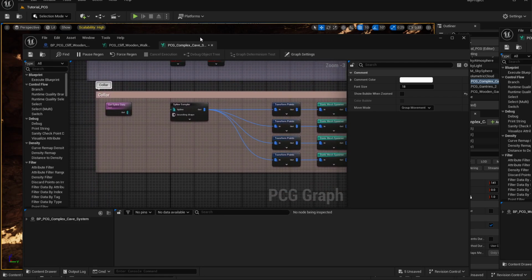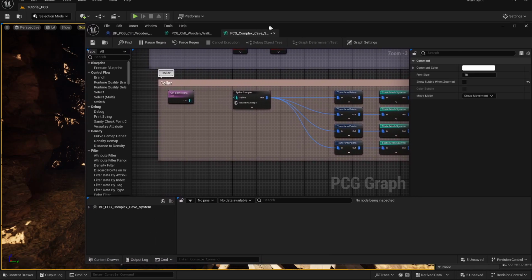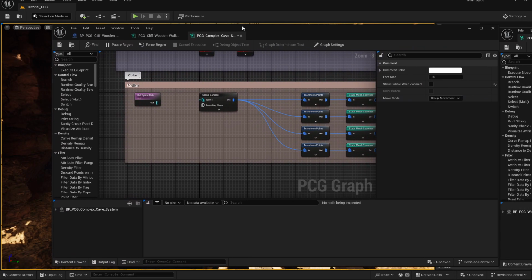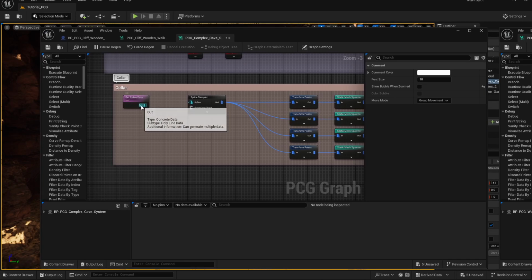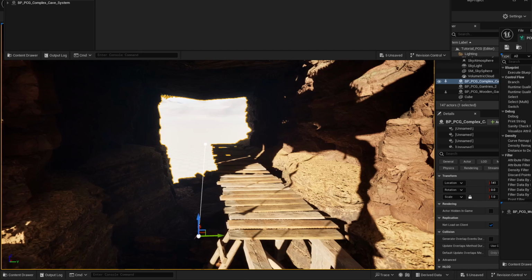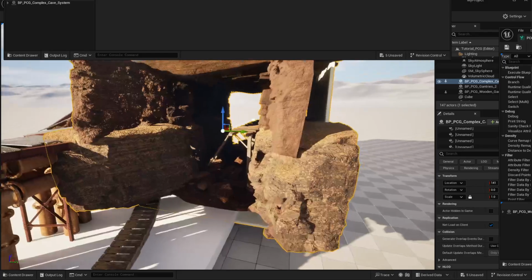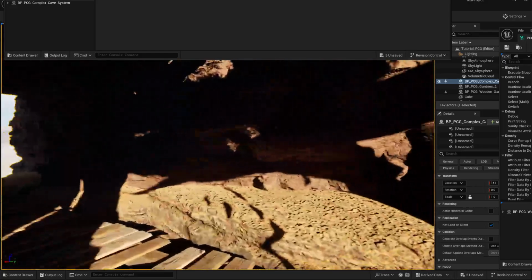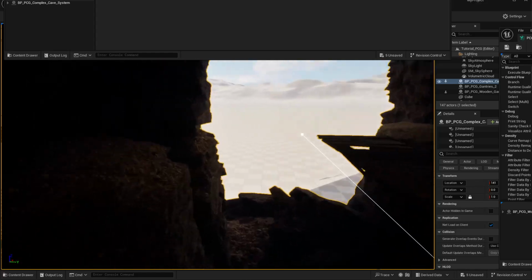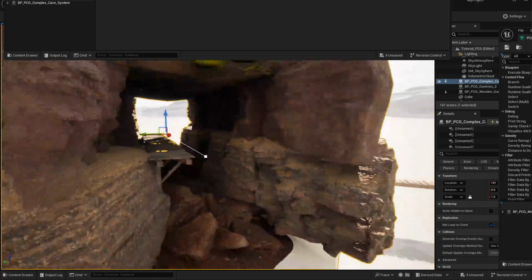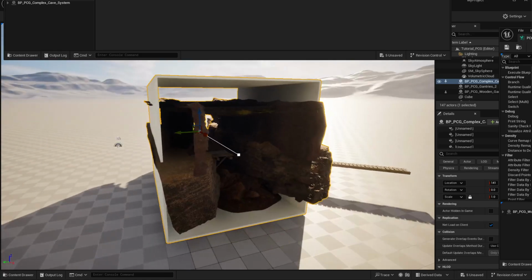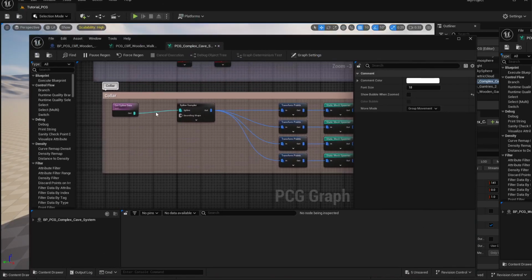And then over here, this thing called a collar is basically the boundary that I set around it. And it's not connected at the minute, but this was to control shadowing. If I connect it together, you'll probably see it. I don't know if I've got it set up properly. There we go. And this was just to control shadowing, if I was using this in an area where I didn't want any shadow to come through any gaps where the meshes weren't quite created together. So this is just a collar going around the outside of it. I can turn that on and off.